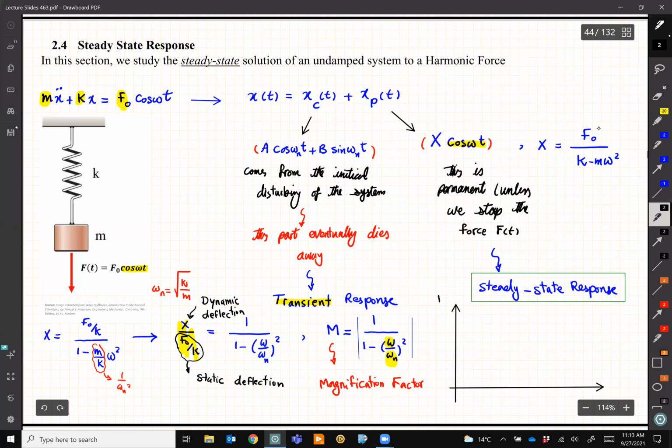So we call this one M, and on the x-axis, let's call it omega over omega n. Okay, it's just a simple function, 1 over 1 minus the variable. And you know how to plot it. So we need some key numbers here. If I look at these, again, don't forget, this is the absolute value, right? So when omega over omega n is 0, like on the x-axis, when I'm at the beginning, 0, this M is going to be 1. So maybe 1 is an important number.